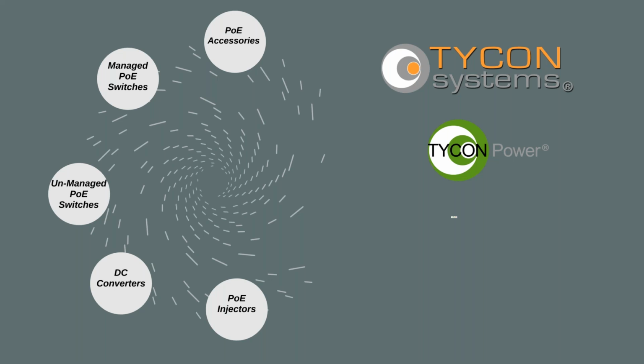Yeah, absolutely. Most PTZ cameras that I've seen, because we do system designs all the time, so we're always looking at other manufacturer data sheets. And to be honest, that's where we get a lot of our inspiration, is having to power those different devices. Most PTZ cameras are going to take 50 to 60 watts, which would be a PoE++ or a high PoE. Or I have seen on the rare occasion a 90-watt PTZ camera. We have the devices to power each of those.